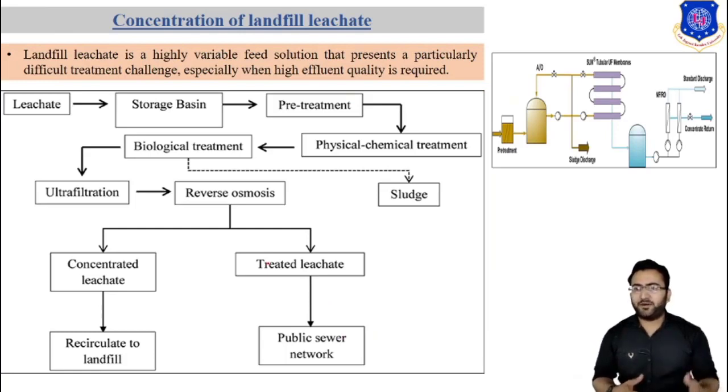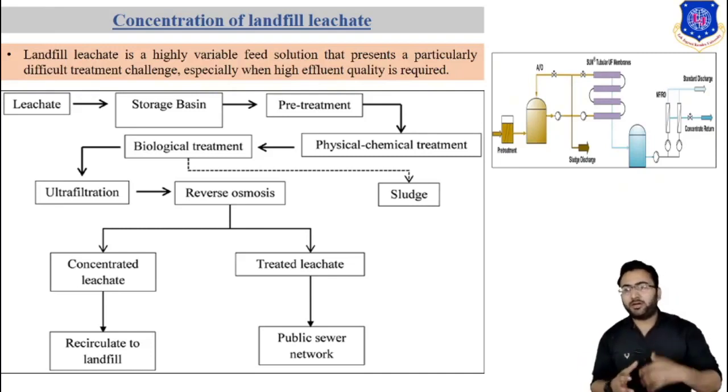Now let's discuss concentration of landfill leachate. Landfill leachate is a highly variable feed solution that presents a particularly difficult treatment challenge, especially when high effluent quality is required. It is a complex solution consisting of four general types of pollutants: organic compounds, dissolved heavy metals, organic and inorganic nitrogen, and total dissolved solids, known as TDS.